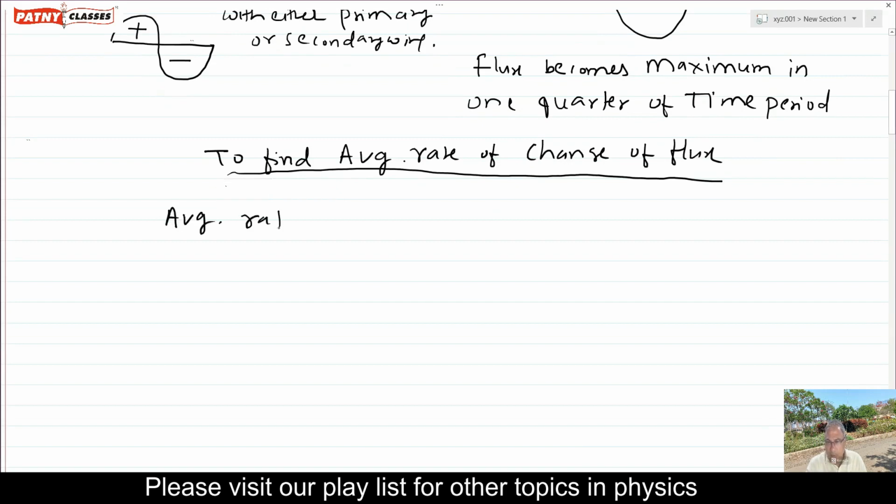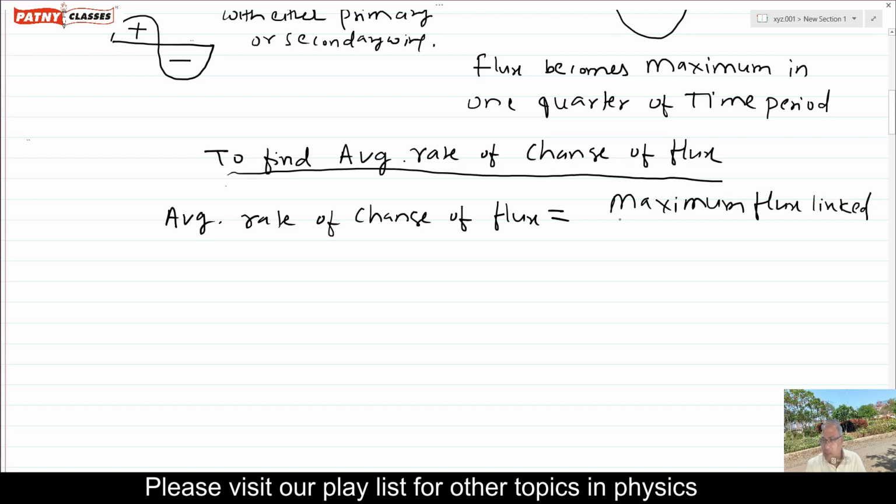Average rate of change of flux equals maximum flux linked either with the primary or secondary coil upon time taken, that is maximum flux phi m and time taken equals T upon 4.